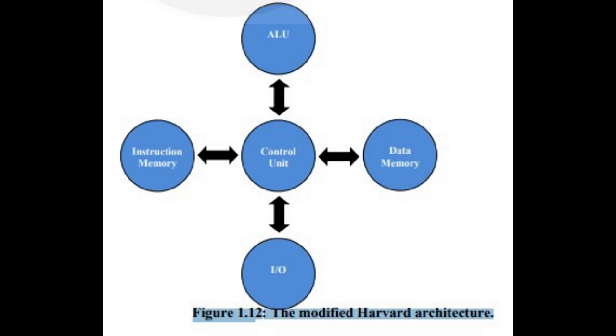1.6.2 Harvard architecture. When data and instructions are kept in separate memory, then it is Harvard architecture. Data is fetched from one memory location and instruction is retrieved from a separate location. Pipelining can be done in this architecture. It is complicated to design. In this architecture, the CPU can fetch, decode and execute instructions and data. The construction of this architecture has separate access for codes and data.